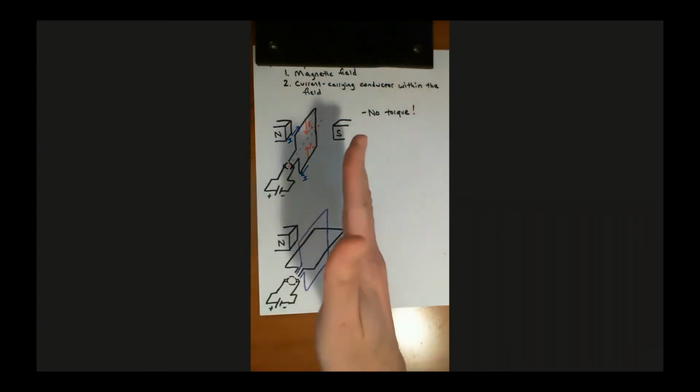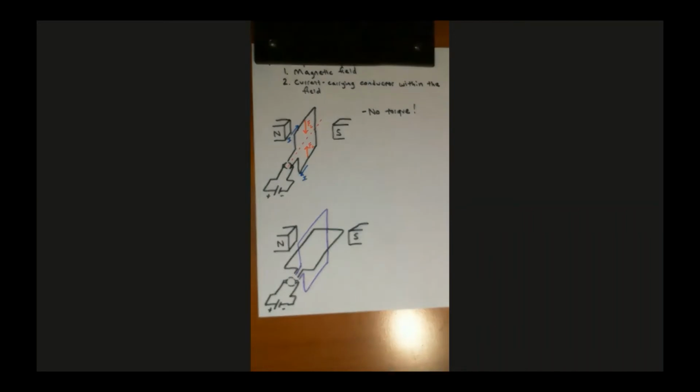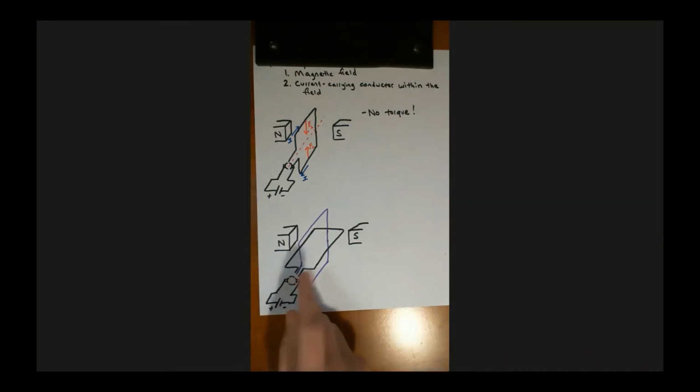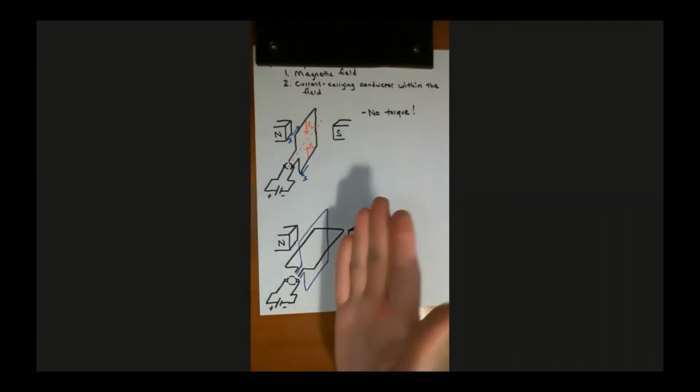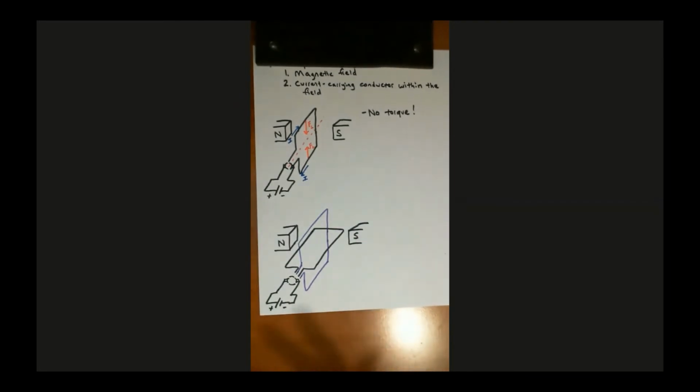But then after this thing rotates by, say, 45 degrees, then now we're going to start applying the voltage to the purple coil, and the split ring commutator segments connected to the black coil are no longer going to be connected to the brushes. So this thing is going to rotate around, and we're going to alternately apply voltage to the black coil and then the purple coil, and the black coil, then the purple coil. As we rotate this around, our voltage will be applied to a different coil as this thing rotates, so that we're always going to have one coil in the armature that is capable of producing torque.